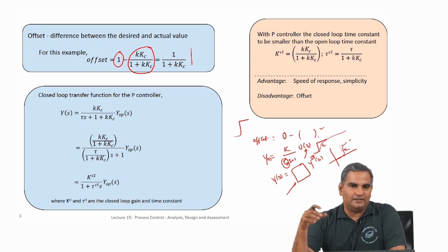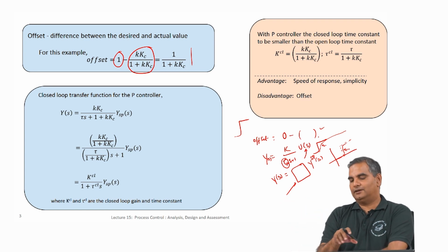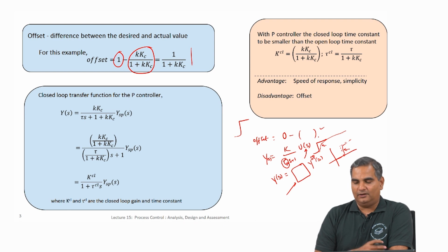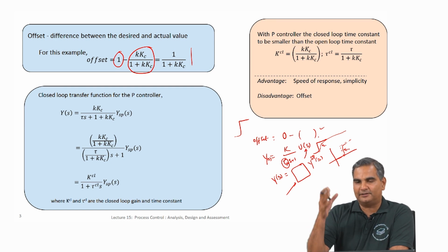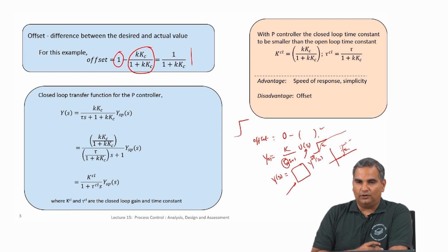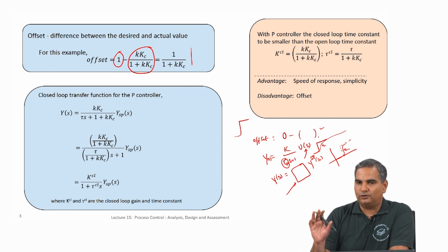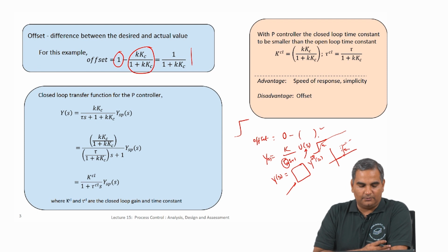As opposed to that, imagine a case where you are simply punching in speeds for the bike and you are not doing the throttling. There is a controller doing the throttling, and you are only giving the set point and not manipulating anything, right. So if that happens, if you press 50 as a set point, you would want the bike to get to 50 as quickly as possible. It cannot be the same rate at which it went to 50 when you simply got to the throttle position and waited, right. So that is the kind of idea we are talking about. Let us see whether a proportional controller is able to do that.